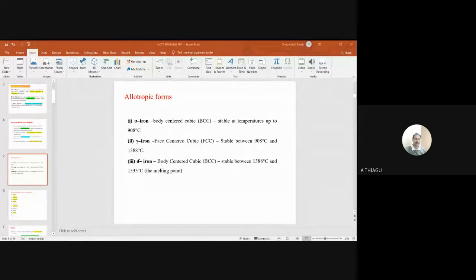So my suggestion, you have to understand the microstructure of the nodular cast iron. Once you find the spherical shape of carbon like appearance, you can confirm it is nodular or ductile, because the ductile is appeared due to the presence of magnesium, sodium.